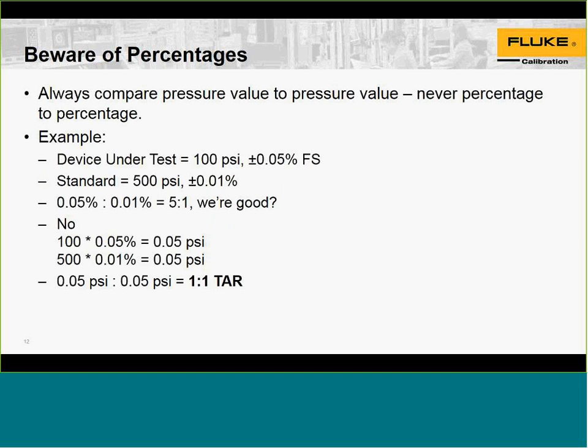I think the big takeaway of this presentation is to be aware of percentages and how they're used. We use a language when we talk about pressure controllers. When doing instrument specifications, it's percentages first, and then we typically convert those into a pressure value. We use percentages because it will simplify and provide a single specification for a model or family of instruments.